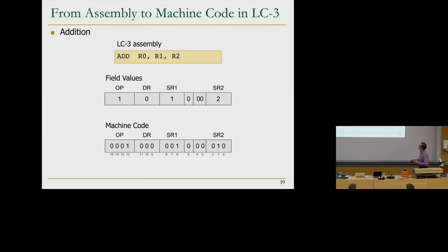It looks like this. And these are the different bits, bit 0 over here, bit 15 over here. The top 4 bits always specify the opcode, which is what the instruction should make the machine do. We're going to talk about that also. And this is the short format. This is basically the machine code. If you want to do it in hexadecimal, it's 4 4-bit values, because LC3 has 16-bit instructions. Okay, we're going to go into a little bit more detail, but that's how you go from assembly to machine